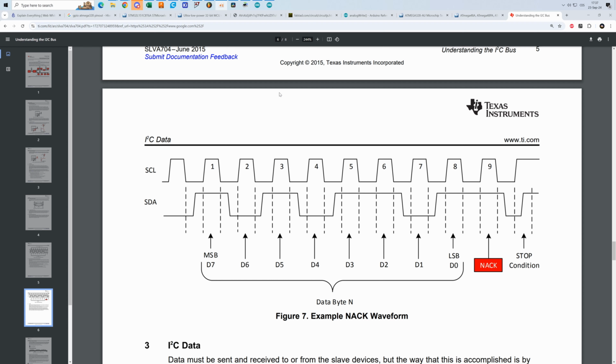Here you can see a diagram of how an I2C protocol works. That's a communications protocol very often used. I'm not going to go into details about how I2C works. That's a topic for another video, but I'm just going to show you that we are using two lines. One of them is for the data, one of them is for the clock. The clock signal is very important because the device and the microprocessor both need to agree on what transmission speed they are going to use.